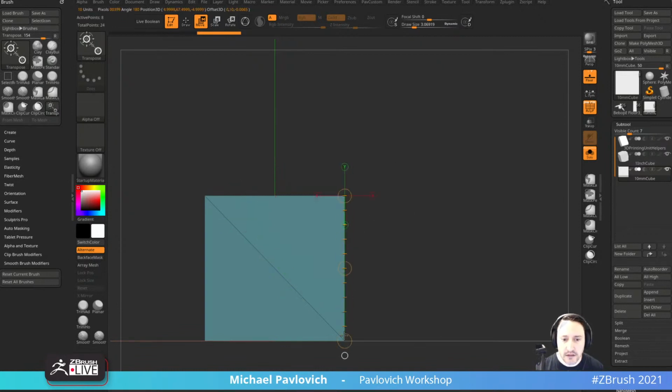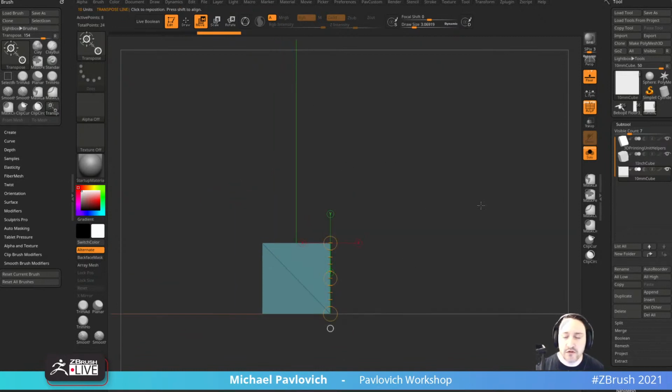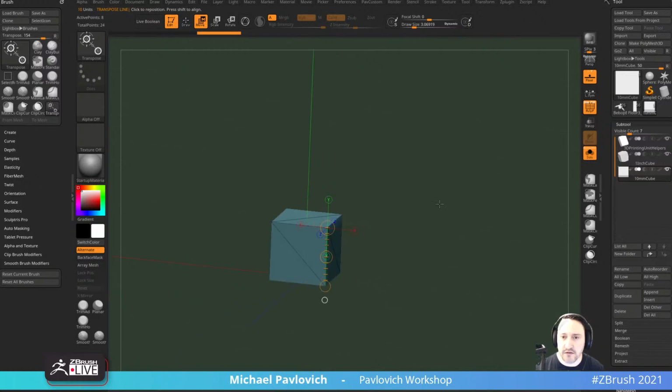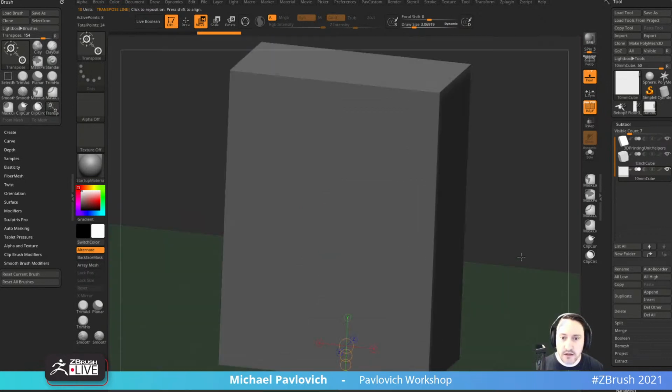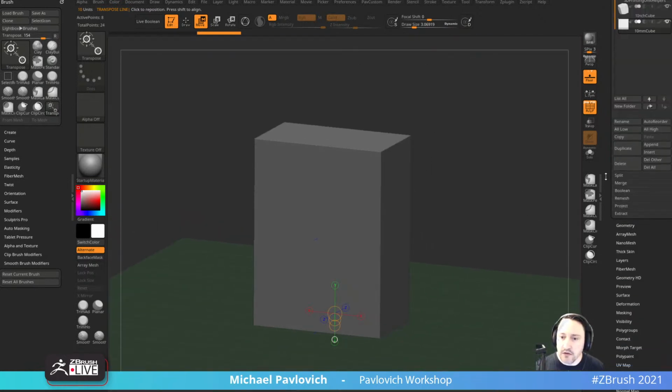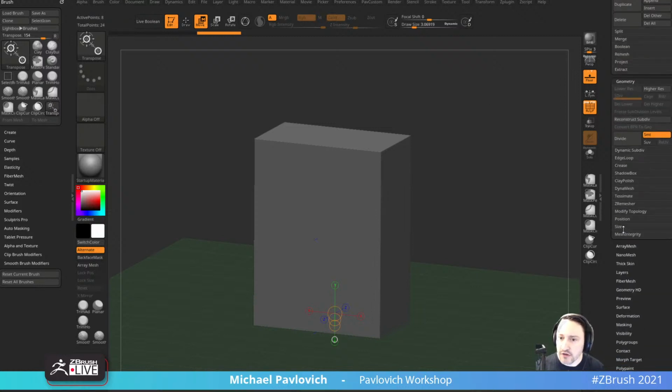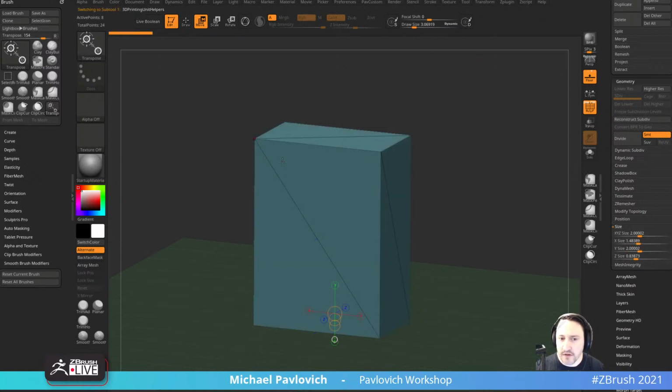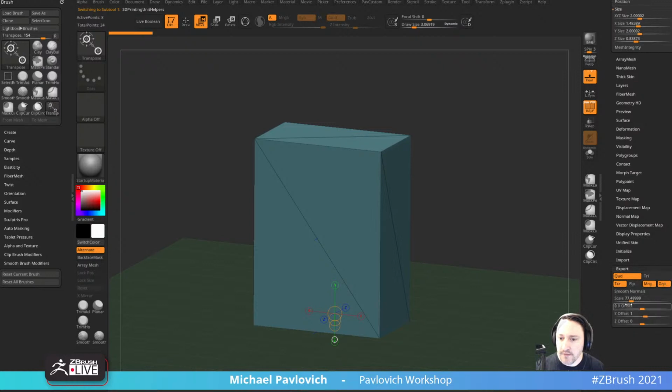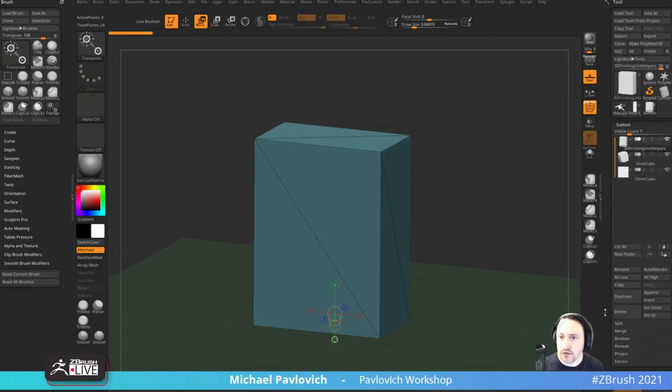So now I've set my transpose units for millimeters, and when I go to export this, it will actually be millimeters as well, because that's what I modeled it in and imported it in. And if I go down here to geometry size, because I imported these, you're going to see this bigger one with the larger bounding box is set to 2, which is good. And then on export, it'll multiply it by whatever scale it needs to in order to be accurate for whatever I go out to.